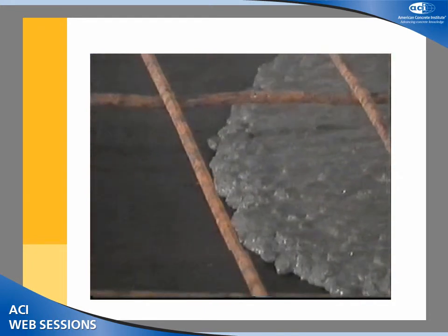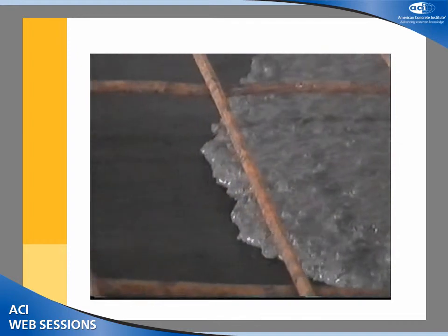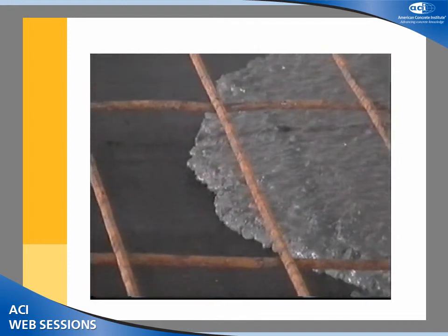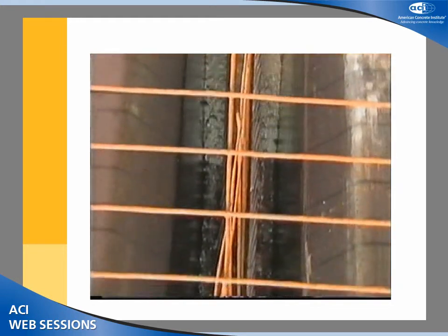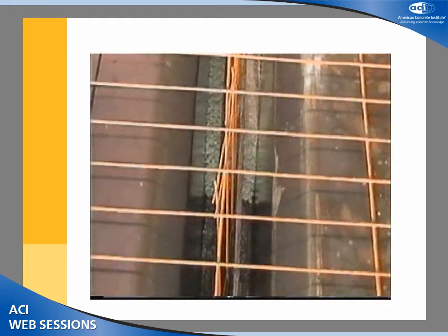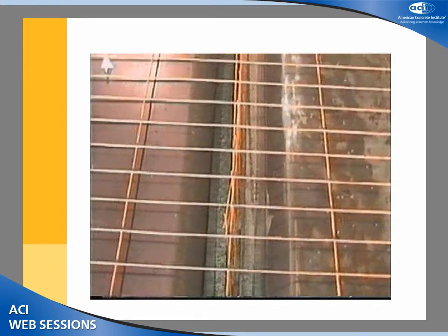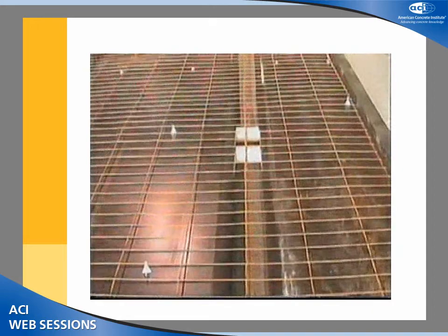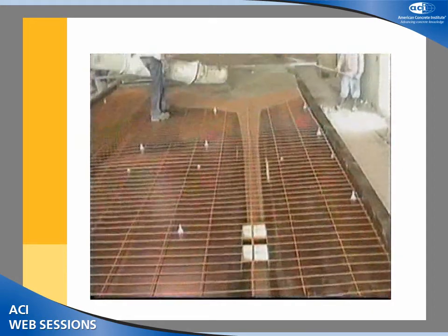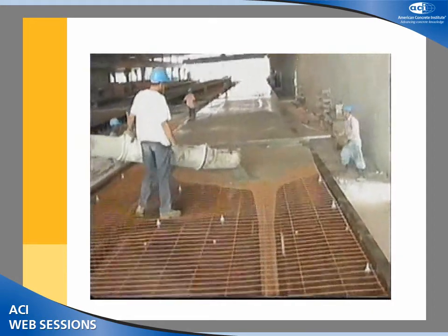Once again, you can see a very fluid mix, keeping a very sharp edge on the concrete, with the stone very much suspended. The same point applies to SCC coming out of a bag in a repair application: it has got to be no different than what you're seeing right now. And this will give you the amount of distance that SCC can travel from one point to the other.